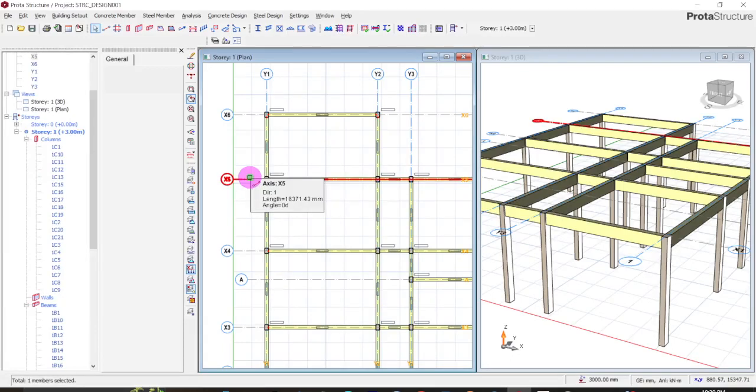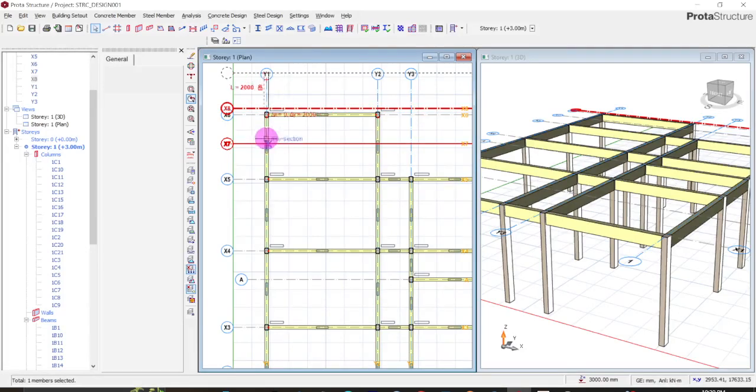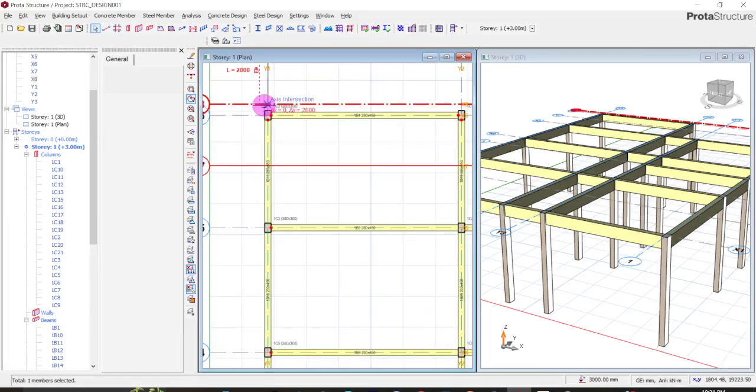So you come on this axis, right click, say offset, press Shift F2, and write 2000. Let's just use an arbitrary figure. Let's assume that's the center, and then we can also come up to there. Say another 2000 just to keep it uncomplicated. Shift F2, write 2000. Yes, let's assume this is a bit too.